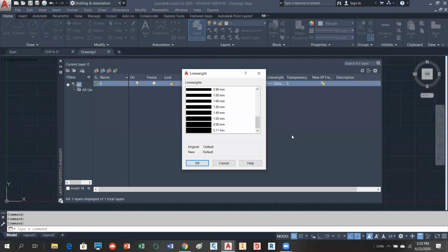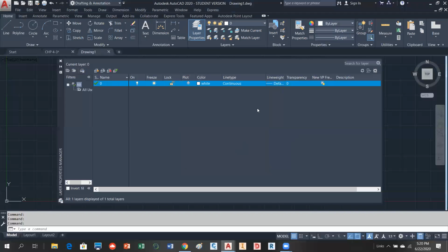And you might remember me saying that in the future, we're not going to be needing polylines as much because we can give all objects line weight now, pretty much. So there are a few objects that will not accept line weights, but most of them will. And one I'll show you tonight that we're going to look at won't put a line type or a line weight on it, okay? So you don't have to load those either. Those are there also automatically, okay?